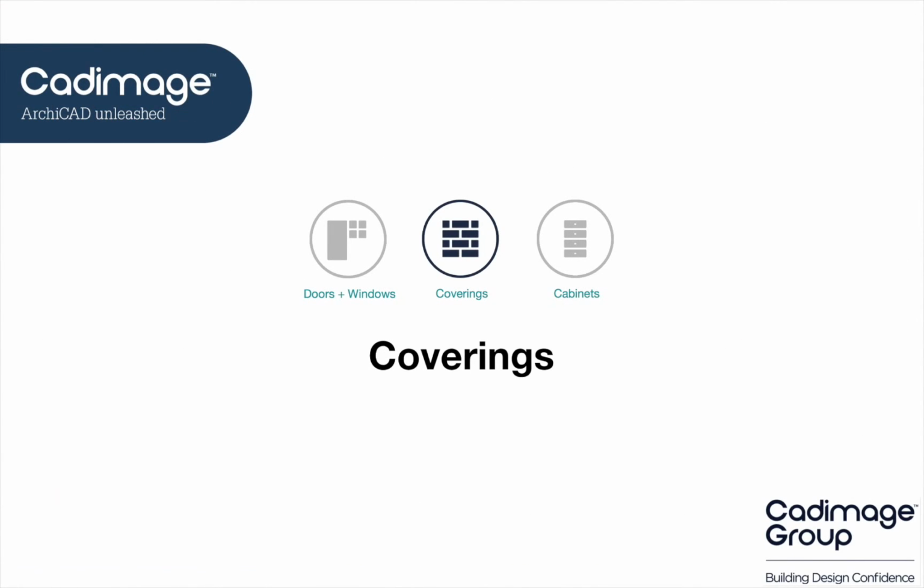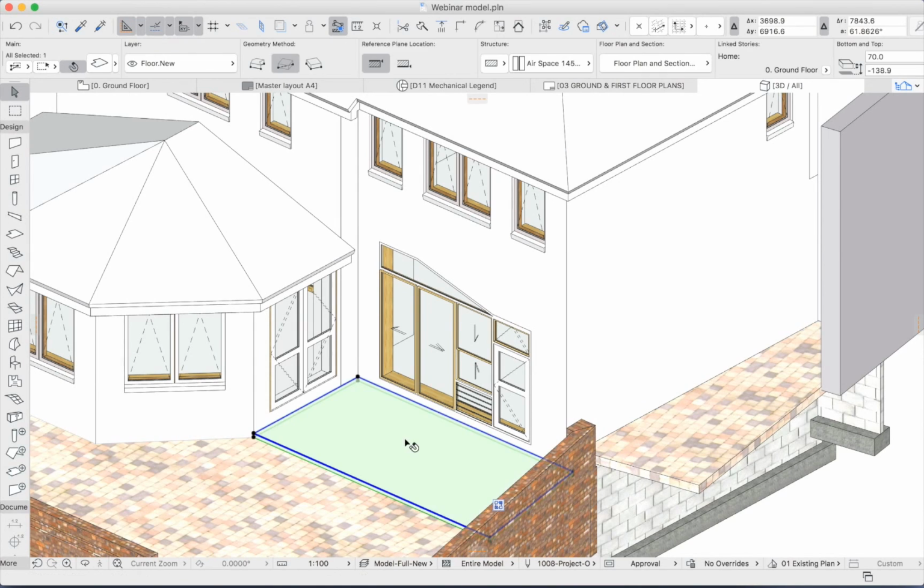Now I'll move on to coverings. This tool is all about representing cladding or finishes realistically in the model, and we'll look at examples using slabs, roofs, and walls. I'll use this slab as a simple example. Say I wanted timber decking.